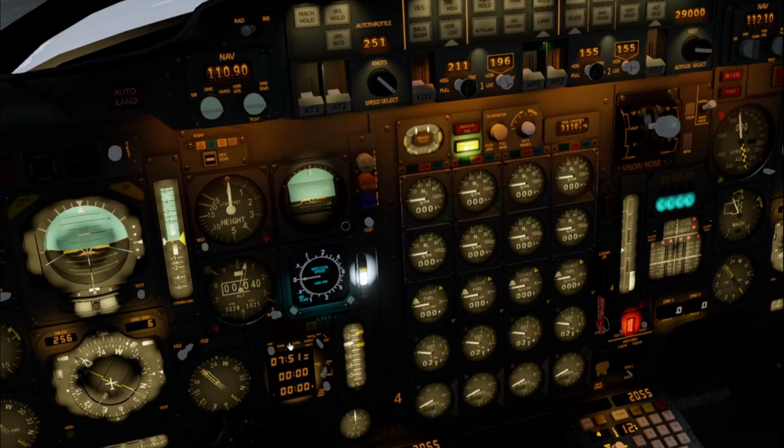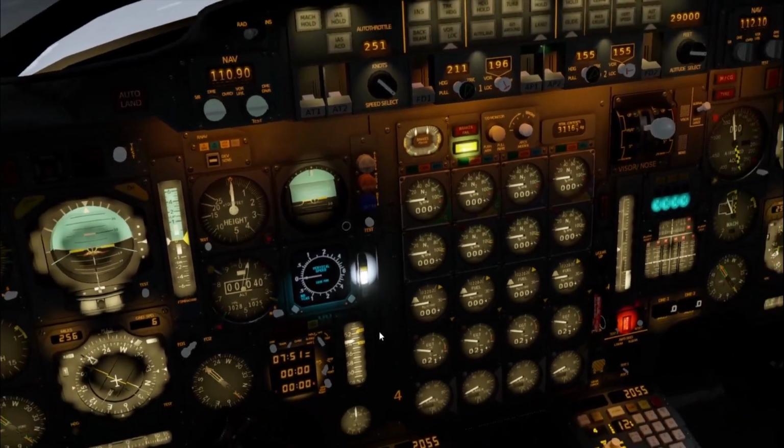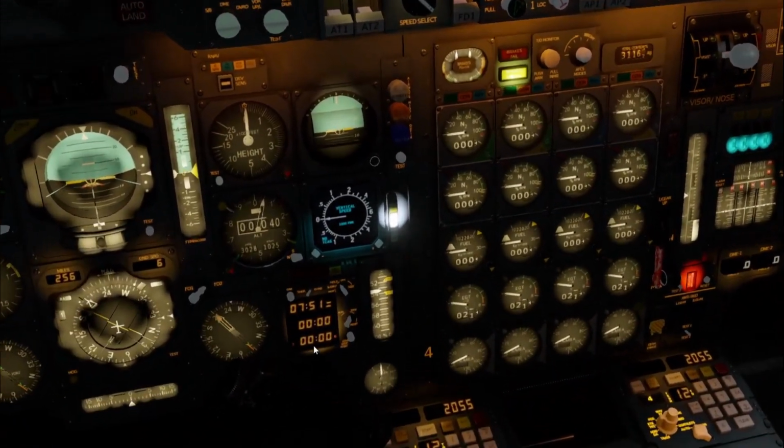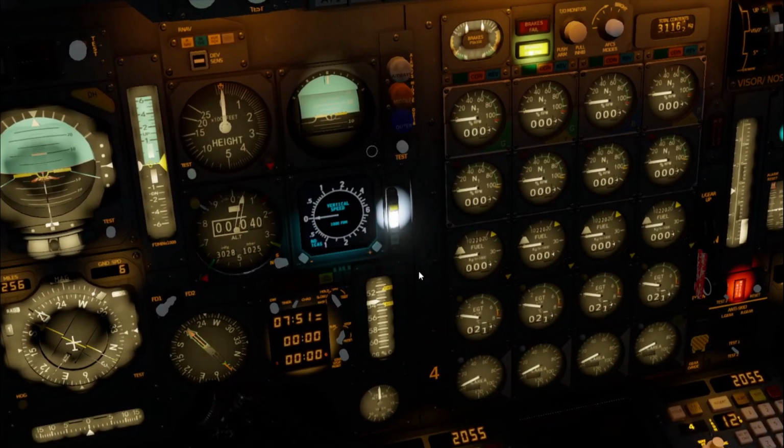We need to set the noise abatement procedure. In premium version there is a countdown to noise abatement procedure. Noise abatement procedure is when you're flying over populated area. After takeoff you should not run at 100% for a long time, and there is a setting.